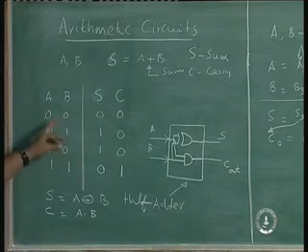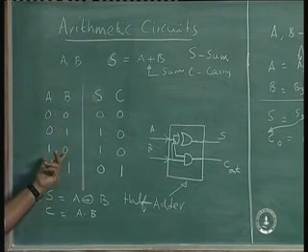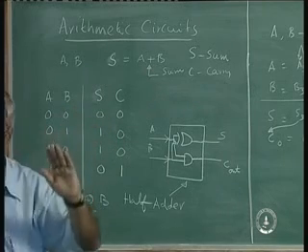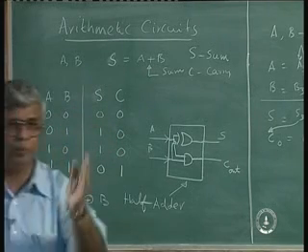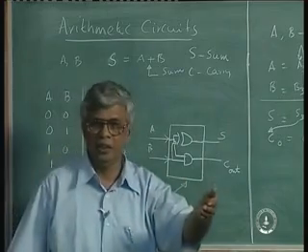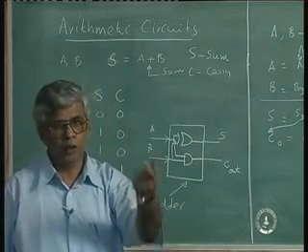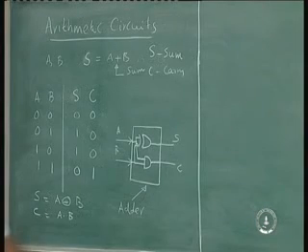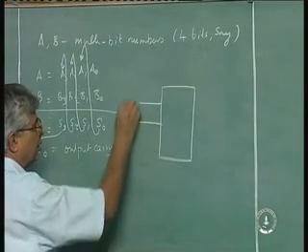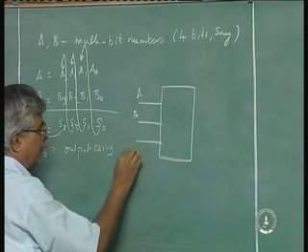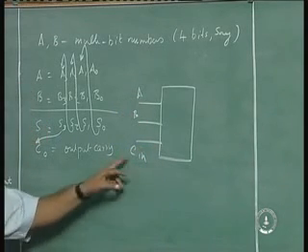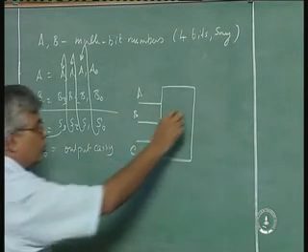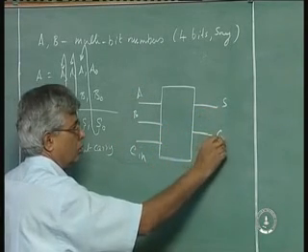A half adder can only take 2 digits and add them to get the sum and the carry, but it does not take into account the carry from the previous position of the addition. I need to expand my circuit into one in which I take my A, B and C in, the C in being the carry from the previous bit position, and get my sum and CO.